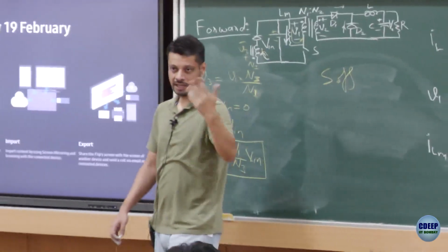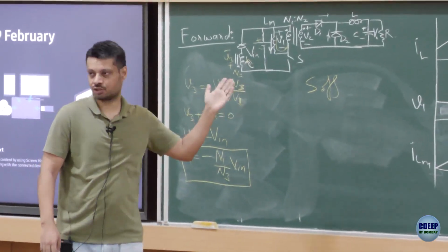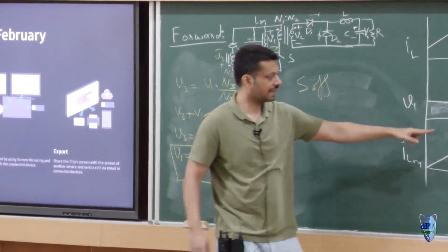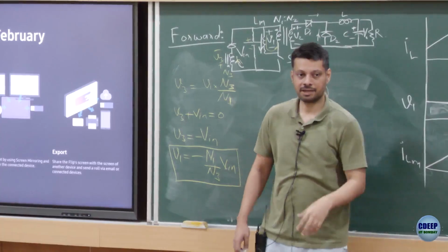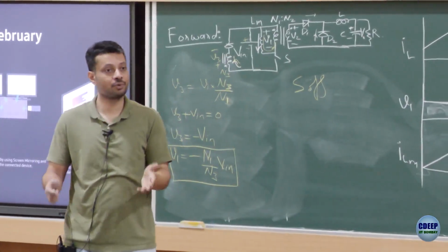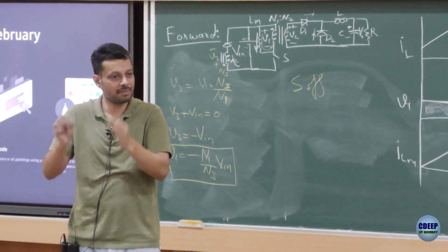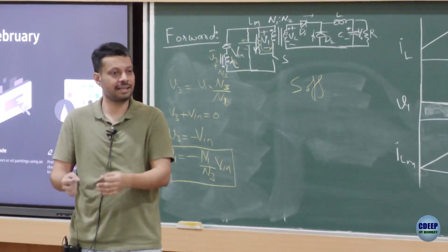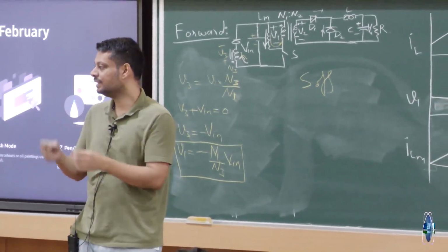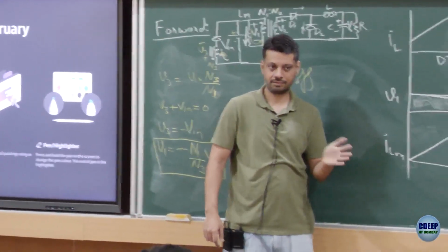And I also said that you can choose a turns ratio N1, N3 accordingly, so that you have sufficient negative voltage, right? But what he is trying to ask is, how are you so confident that you would use specifically the same number of N1, same number of N3, precisely calculated for a Vin, so that you get precisely 0 DC voltage if you average this out? Is that the question?